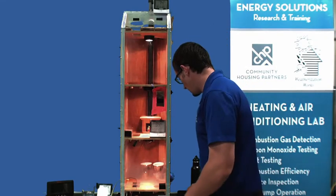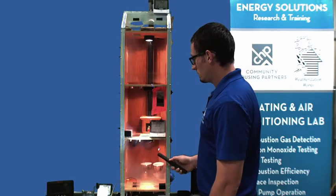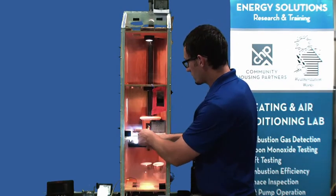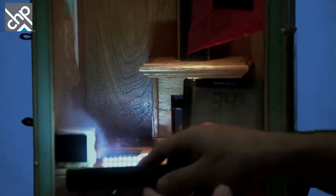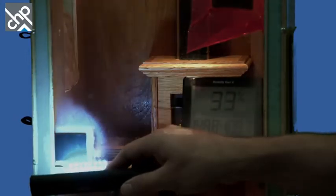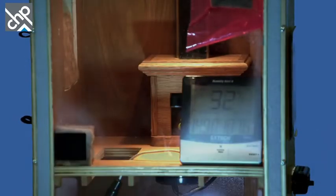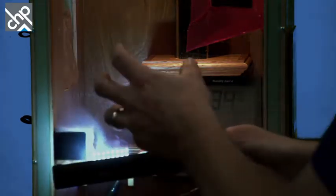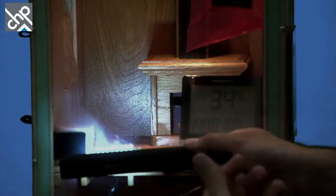So moving on up here, this insulation is trying to keep this surface cool. It's on the inside, can't get to this one. Inside here, 102 degrees. And we're seeing the same thing we saw on the side over here. We're seeing that condensation forming all around there.